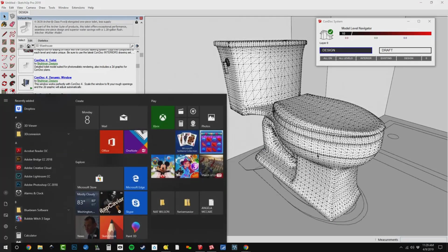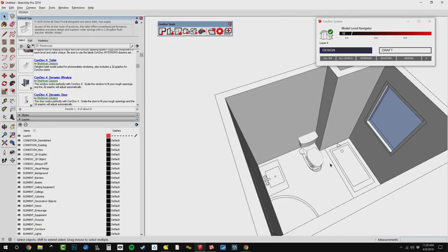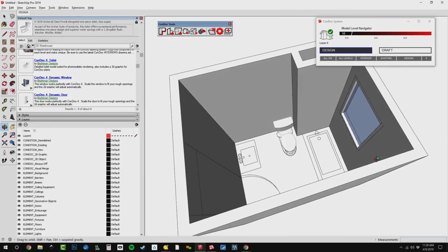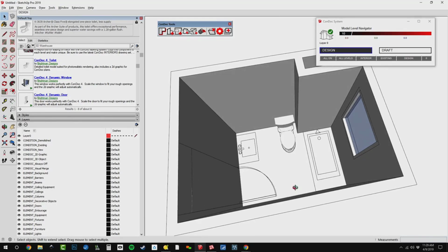This is how we make layout really fast, all right? So, of course, your walls and anything that needs to just be flattened in layout, do it. But be aware that when you are flattening super heavy 3D geometry, that could be a culprit for slowing things down. I think the number one kind of bomb I see in models is cars. When they get flattened in layout, that takes time. It's easy to just make a quick 2D graphic.